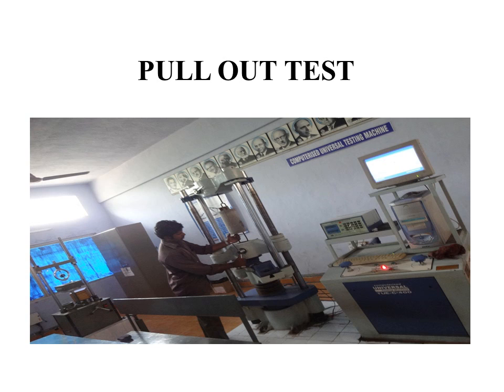This is the pull-out test setup. In this, the specimen has to be placed in position and fixed. The specimen is made up of three different forms of embossment and with plain sheet. The test result has to be compared between the embossed sheet and the specimen without embossment. Actually, we are using three different shapes of embossment: chevron, tablet, and rectangular shape.